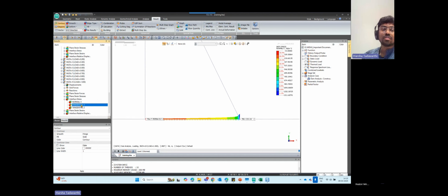And then we have tangential stress. Go for tangential Y. So you can see this is a tangential force, which is actually the sliding force. Since we have the hydrostatic pressure and the uplift pressure as well as tailwater pressure, the hydrostatic pressure is the one which is letting the dam slide, and we have around 50 to almost 950 in terms of pressure. We will see whether this is high enough to induce the sliding, or if the factor of safety is greater than 1 or 1.5 over there. So that's the stability check. I will come to the extraction and the calculation at the end.